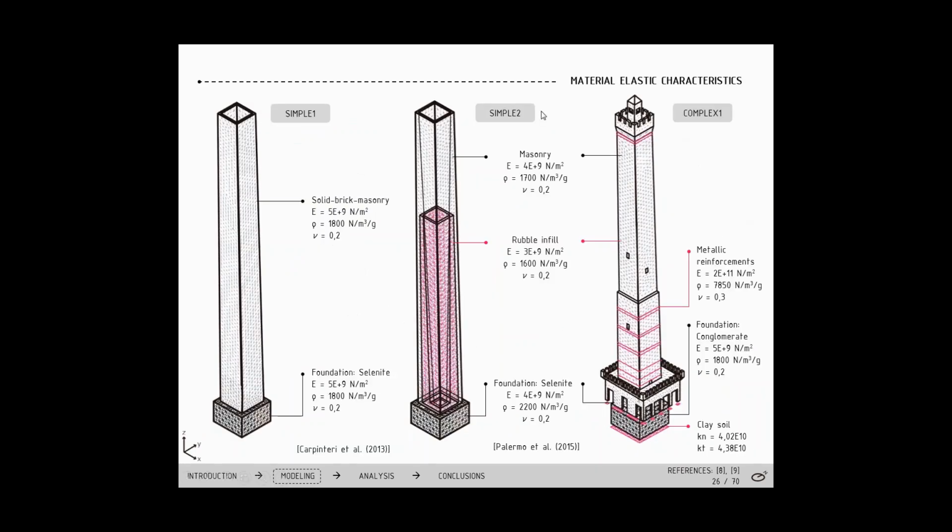So this is how the final models look discretized. The isotropic material properties used can be seen also in this slide. For the first model, the properties are obtained from a model identification study made from a similar model of this tower. For the second type of model, the properties used are extracted from experimental tests done on the actual tower and model identification theoretical procedures on higher complexity models.